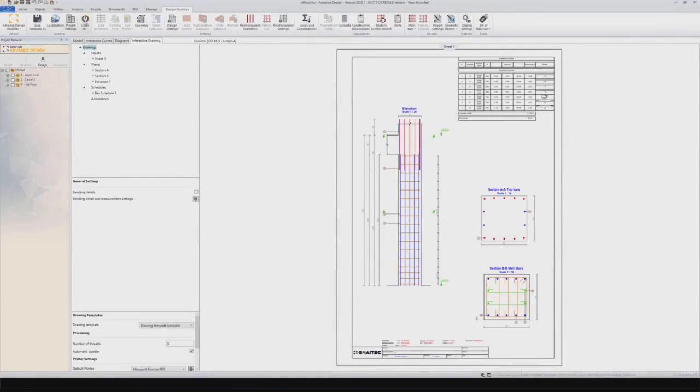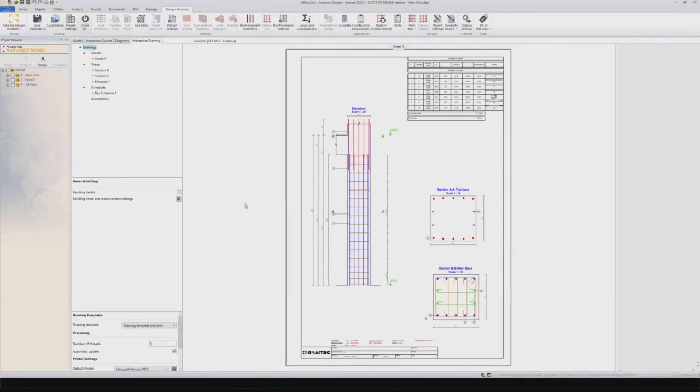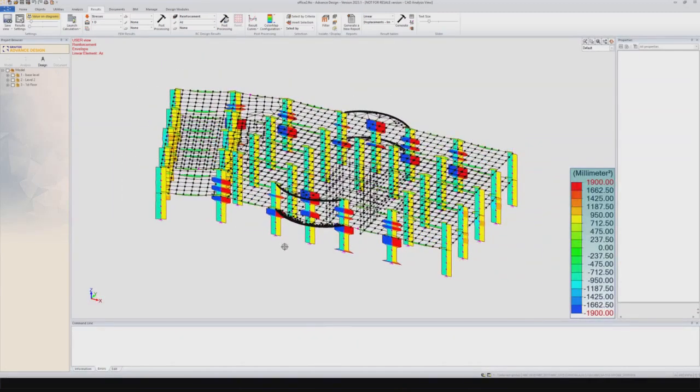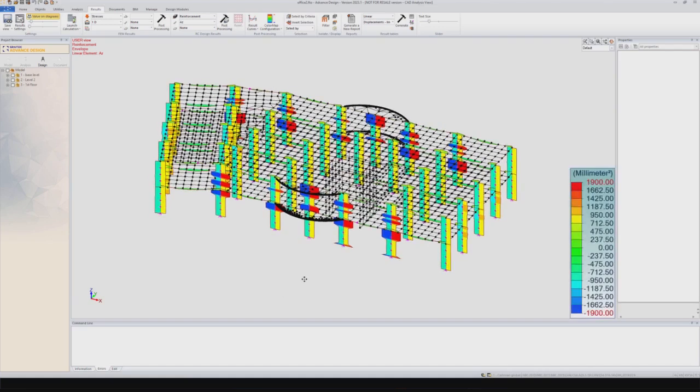Now, because this webinar is about a concrete workflow, now I'm going to show you how we can actually send back our model, which is created now, back to my Revit and synchronize my elements. Okay, so we can see more stuff there. So just to show you the changes and how the changes can be imported inside Revit using the synchronization, I will just go back to my model and I will modify the section of this column.